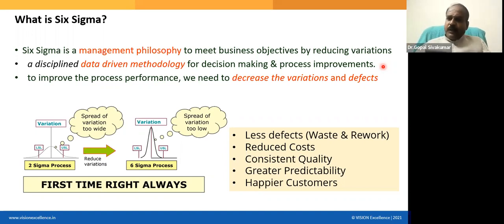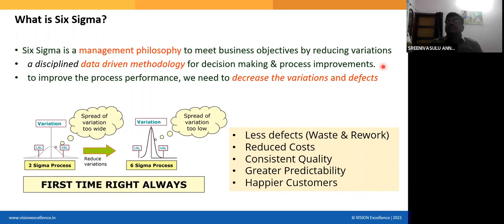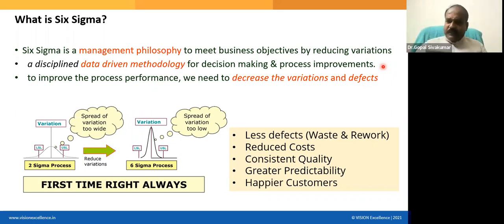Will you be able to give me all 10,000 pieces exactly 10 mm? No, sir. Impossible. Companies have even tried setting up manufacturing facilities 100 feet down the ground to ensure they produce close to the tolerance, to ensure the variations are less. Because when you set up your factory on the ground, there are a lot of vibrations happening, and then variations are possible. So they have even tried going down by 100 feet. Then also they experienced variation. So variation is a rule of nature.